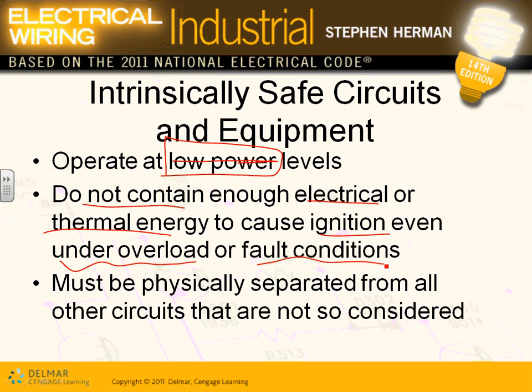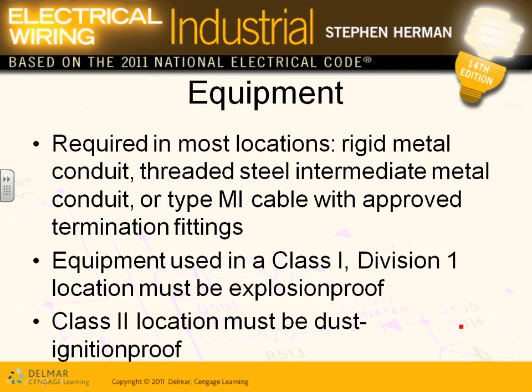So the other thing, when you put them in EMT, you have to put them physically separated from all other circuits that are not so considered. Mostly for sensors, mostly for control circuits, guys, you put them in different EMT conduits. You have to seal the conduit still, and you go to this equipment to sense what's going on. Guys, you have oil refineries. There's tons of these. You think about oil refineries, not just gas stations, and so forth. You have to have a lot of sensing equipment everywhere.